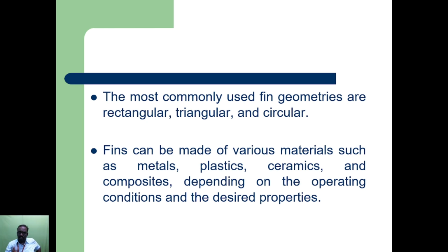Fin efficiency also varies; using the heat transfer data book we can see the effectiveness and efficiency formulas for various geometries, and calculate how energy transfer takes place in fins. Fins can be made of various materials such as metals, plastics, ceramics, and composites, depending on the operating conditions and desired properties.